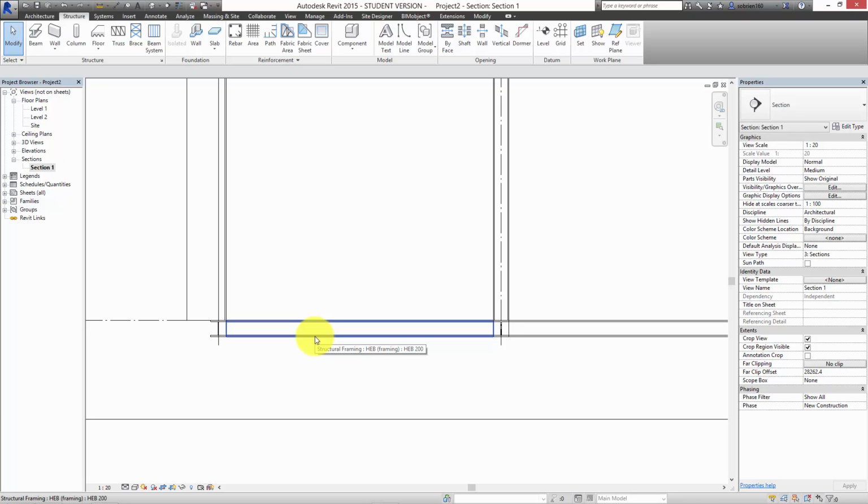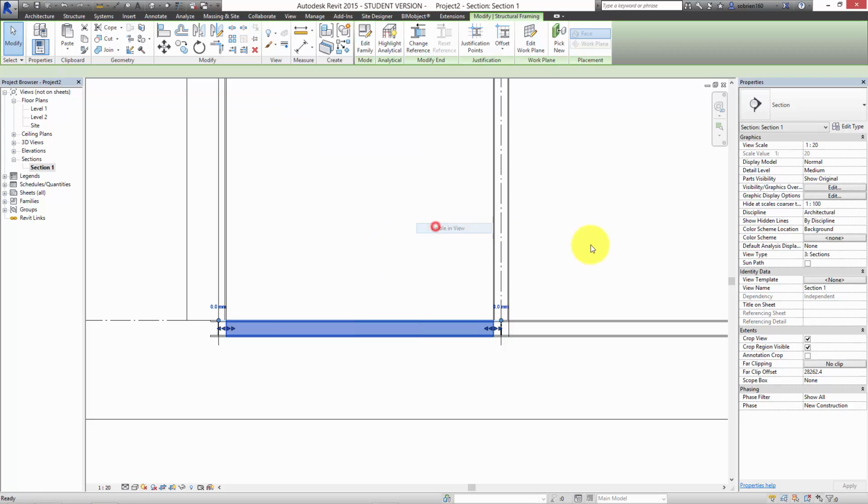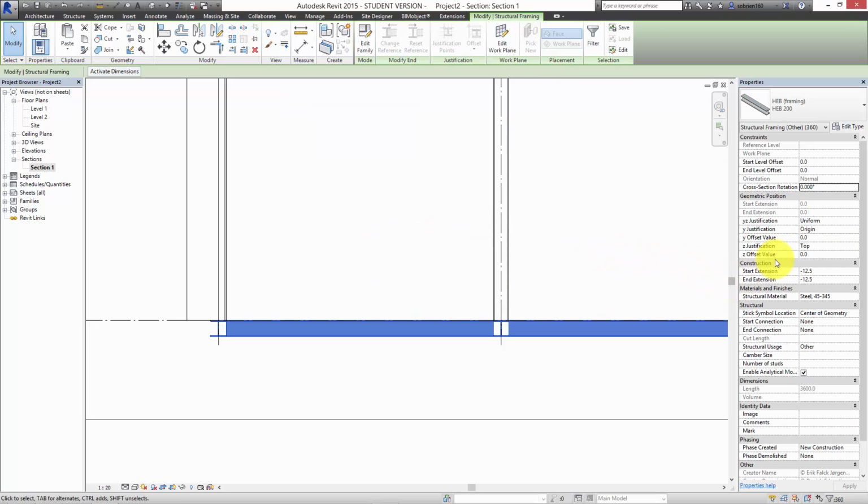So what I'm thinking is that in this case here, you would have probably overlaid your structure on top of an architectural model you've already made. You've already divided it up into timber floor, some kind of resilient layer, maybe some insulation, some concrete or whatever. So you would treat the structural element as being an element within the concrete there. So if I select all instances in View, I can give it a Z offset value, Z being the vertical dimension in geometry. And let's say we want to minus it 50 and apply it.